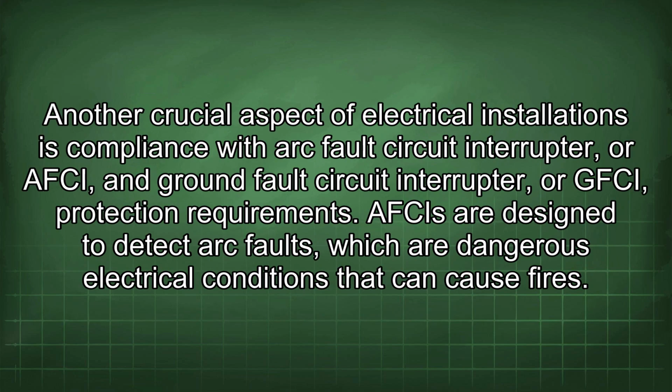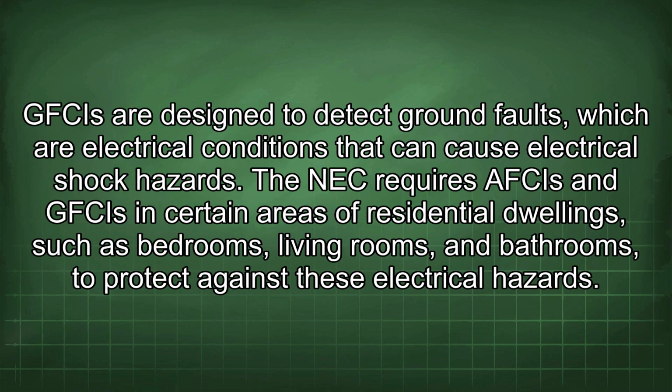Another crucial aspect of electrical installations is compliance with arc fault circuit interrupter, or AFCI, and ground fault circuit interrupter, or GFCI, protection requirements. AFCIs are designed to detect arc faults, which are dangerous electrical conditions that can cause fires. GFCIs are designed to detect ground faults, which are electrical conditions that can cause electrical shock hazards. The NEC requires AFCIs and GFCIs in certain areas of residential dwellings, such as bedrooms, living rooms, and bathrooms, to protect against these electrical hazards.